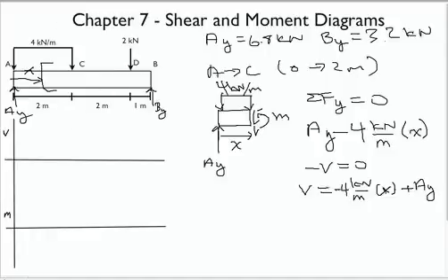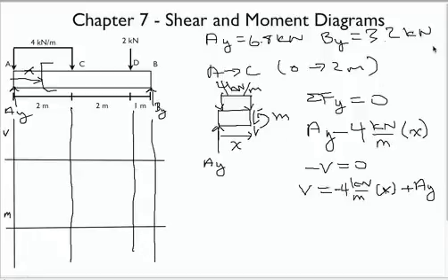All right, so we can go over here and I'm going to draw some green lines here, maybe those are green, I don't know, I'm sort of colorblind. Some separation lines here, they're not, they're black. And to help us separate this shear and moment diagram out in these pieces. Okay, so at x equals 0, or the beginning of the beam, our shear is equal to AY. And so AY in this case, right, is 6.8. So we'll put a little dot here. We'll write 6.8. So there we go.